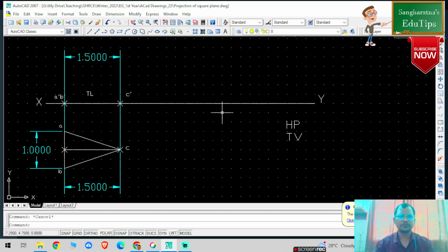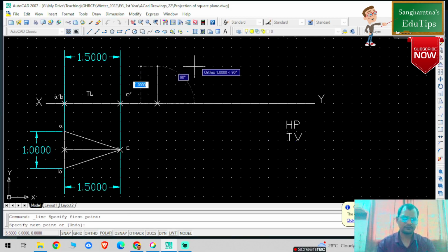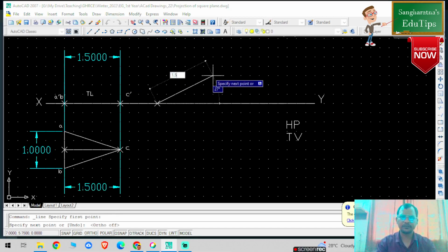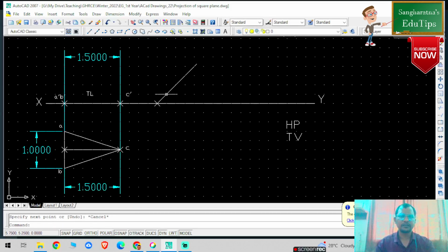So I'm selecting any point on this reference line, say here, and from this I'm going to draw a line of 1.5 AutoCAD units, click on ortho, press tab, and the rotation angle is 45 degrees. Press escape. So now this is my line of 150 mm dimension, and the inclination given is 45.